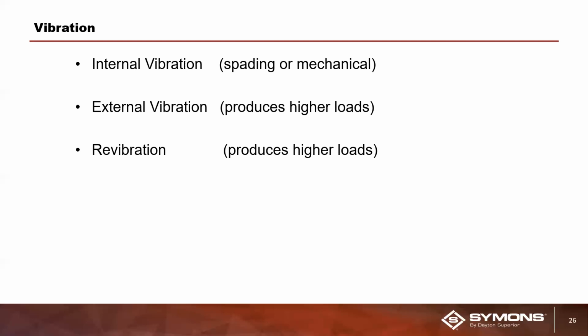Revibration is where you have concrete that's already started to set up in its initial set, and you end up sticking the vibrator head into it, re-agitating it back into a full liquid head. So at that point, you need to start recalculating your load pressures based off of where you stopped revibrating, and based off of concrete height.